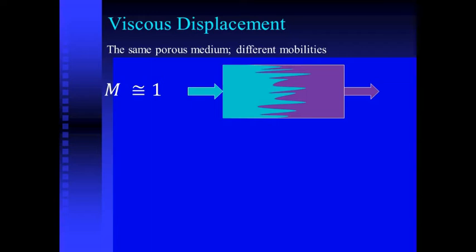In these conditions, what we know as viscous fingering occurs, although the phenomenon is limited. At the time represented in the image, we are only injecting water through the inlet face and only oil is being produced through the outlet face, since the water has not yet reached the production end.